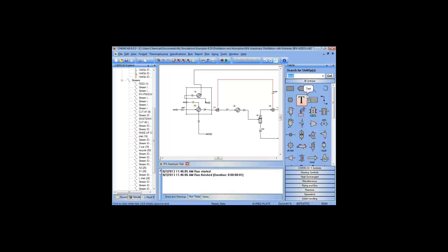If this is an important project and I'm sick tomorrow, or I get sent to a different important project, I think we all know that feeling, priorities changing, and I have to go out of country for a month, someone else might be told, here's a simulation, finish what David was working on. They might not know what I know, that this is two heat exchangers for calculation purposes while I try and find the answer. So while I'm doing this, I might put a box around them and I might put a note on the flow sheet: one heat exchanger, trying to converge recycle. I might even put do not build two.